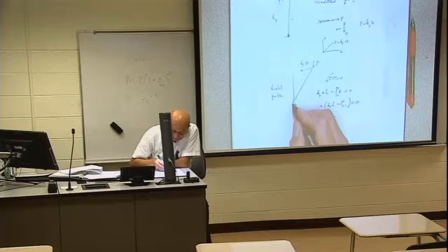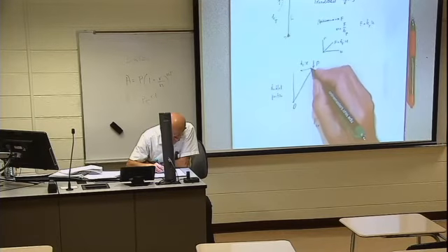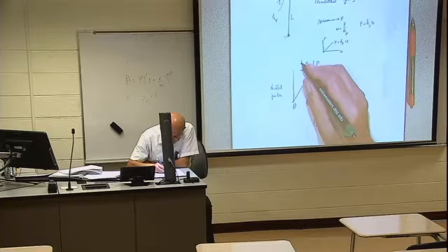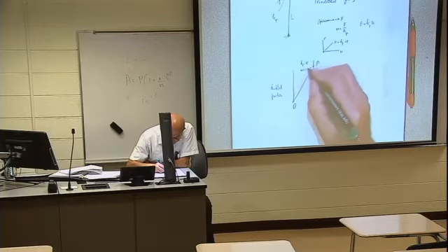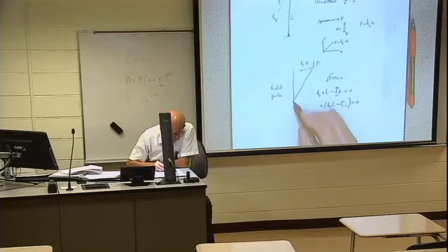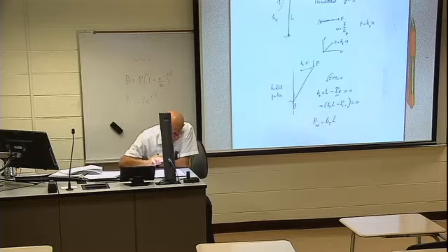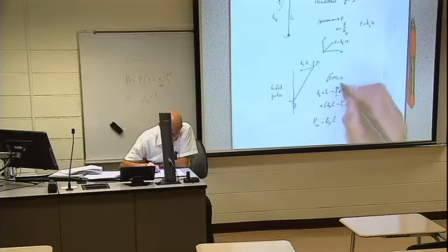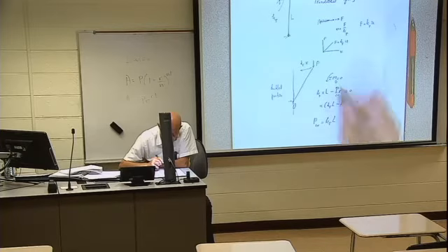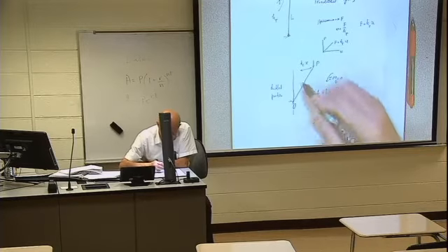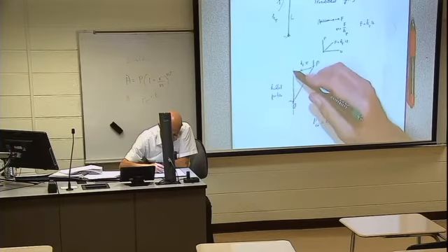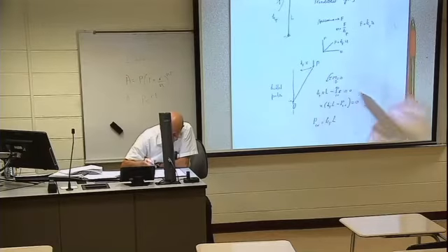There is this load, and then the spring load will be K translational X. That is this displacement. So I again take the sum of the moments. Naturally there is this load here and the load here, but if I take the moment with respect to this point, all these loads give me 0 moment. The sum of the moments with respect to O equals 0. So the load will be K translational X, and approximately this is the length, because this is a small displacement.